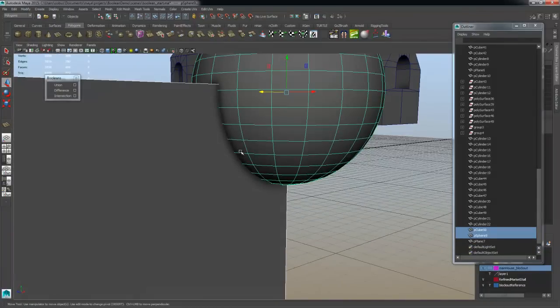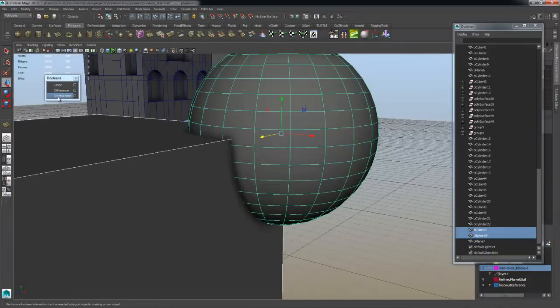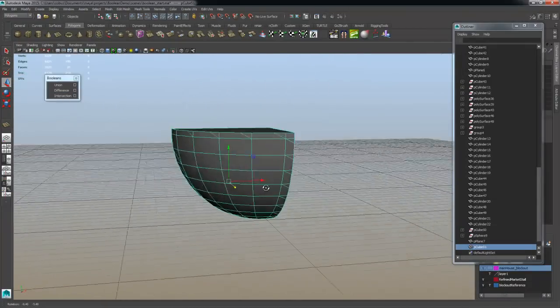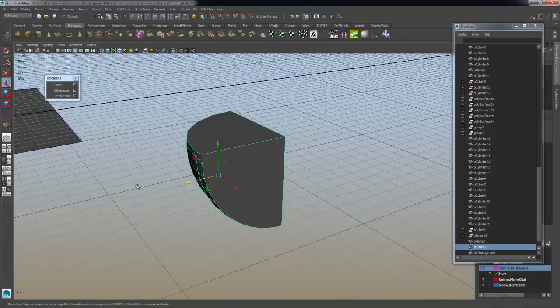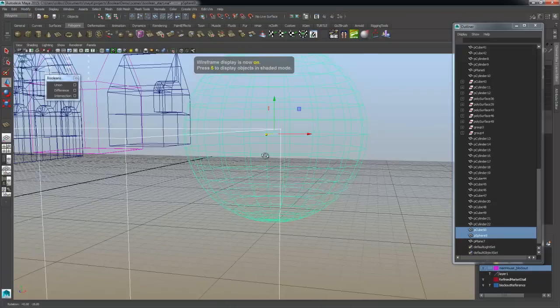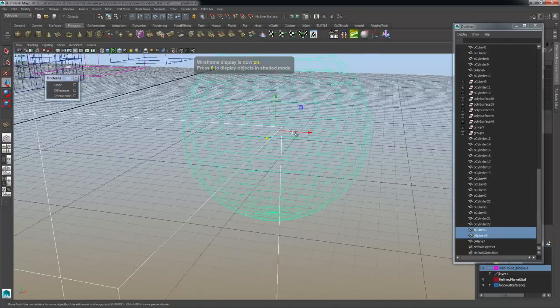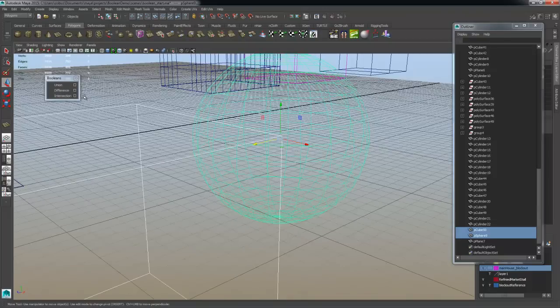So just to demonstrate the intersection piece that I was referring to earlier, if I select them and hit intersect, essentially that leaves the piece that connects the two, the common ground between the two. And if I go to a wireframe just quickly, you can see where these two intersect. That's the piece that gets stripped out, and then everything else gets deleted afterwards.